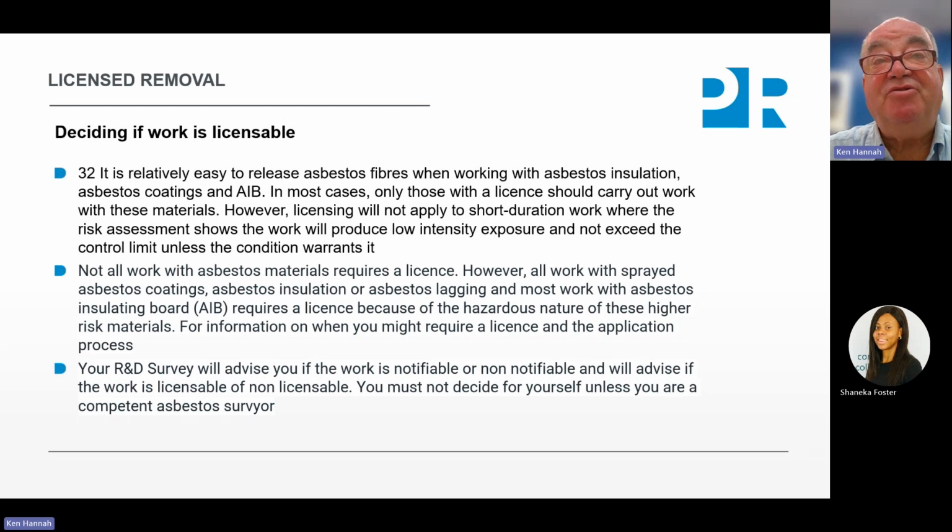So in removing a small amount of tiles, that could be viewed as low intensity exposure and not exceed the control limit. But the control limit, as we'll go on to see, is quite low. Not all work with asbestos-containing materials requires a license. However, all work with sprayed asbestos coatings, insulation or lagging, and most work with asbestos insulating board requires a license because of the hazardous nature of these higher risk materials.